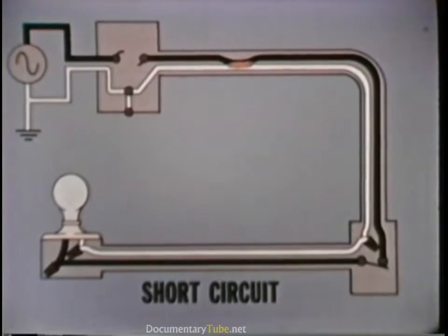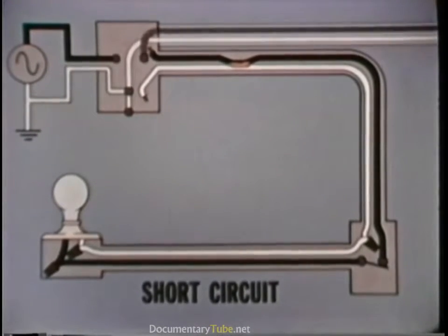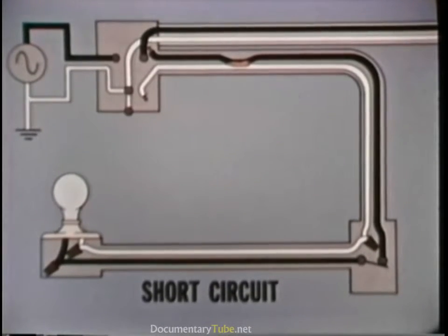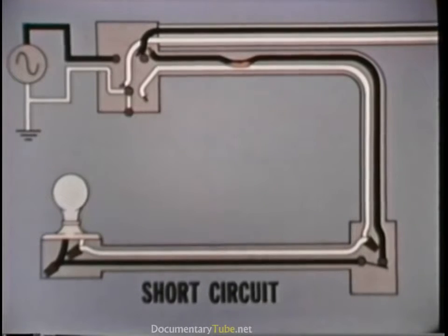To check the wiring safely, disconnect the conductors from the power panel. For the hot conductor, this is normally done by removing the fuse or opening the circuit breaker. However, if more than one circuit is controlled by the fuse or breaker, the conductors must be physically removed from the power connection and separated.